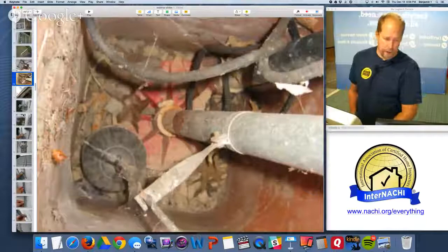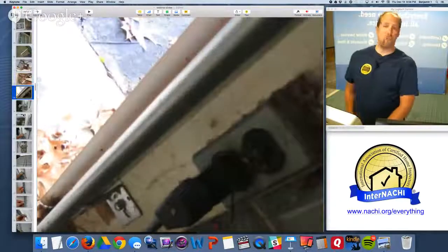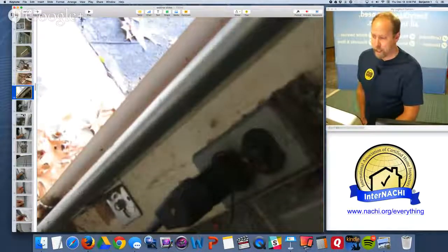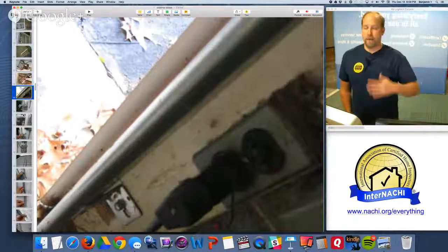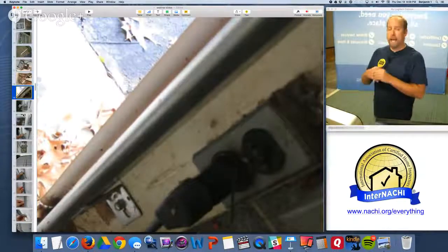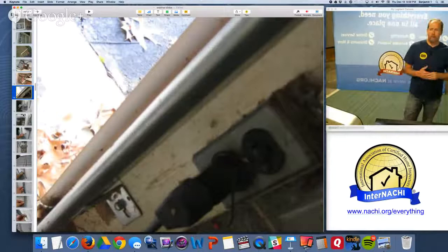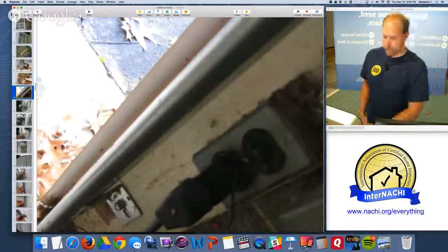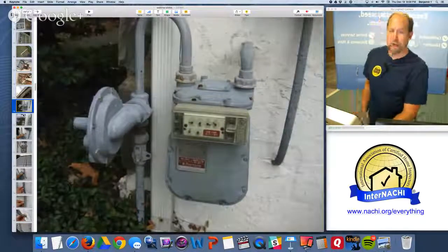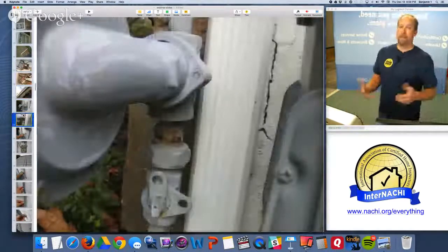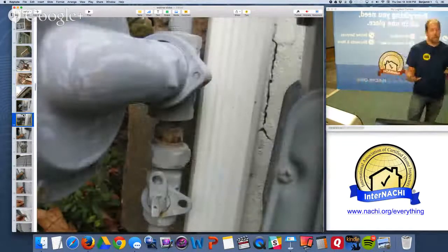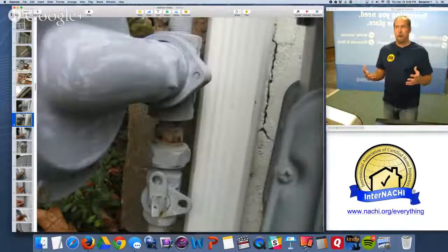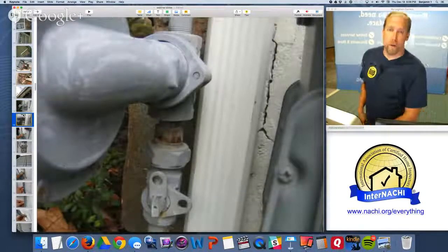Dry, bone dry in there, but indications that there was water. And obviously the gutters are overflowing. The grading is essentially level, and we have water problems in the front with drainage problems in the front of the garage. Now I start to put pieces together. Now I'm gonna look for maybe the crawl space or the basement having indications of prior active water moisture intrusion.